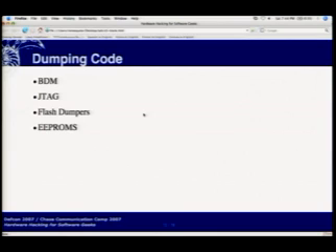It uses some proprietary burst protocol, which is not at all a standard. So for different devices, you have different BDM pinouts. Some of them will be 8 pins, some of them are 6, and all of them require different pods, and it's a very expensive way to do development. Each pod's only about $50 to $100, but if you connect the Freescale pods backwards, it'll short the pod and you need a new one. So you can go through a lot of them if you're using those in your manufacturing process.